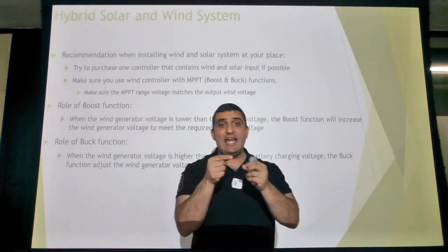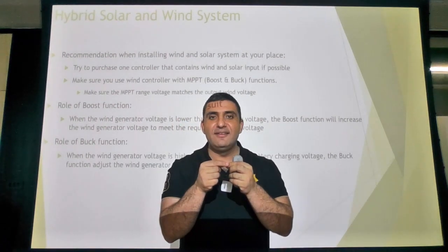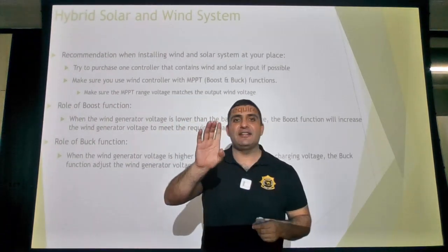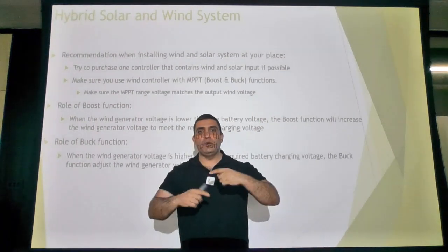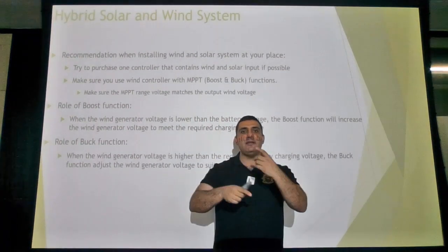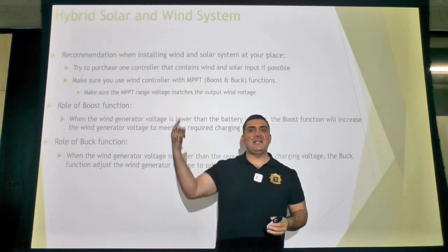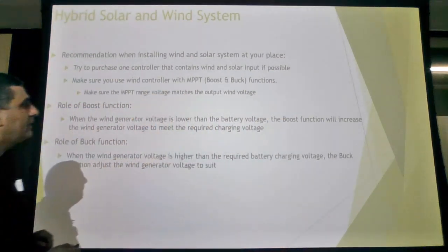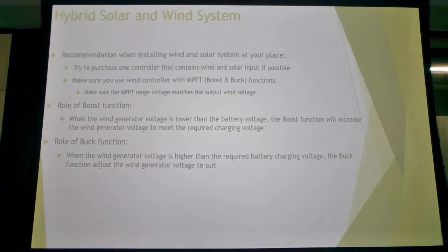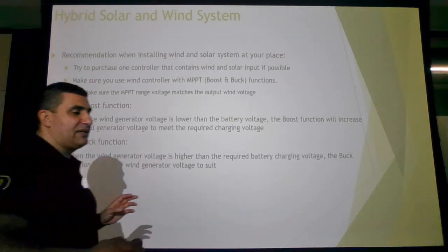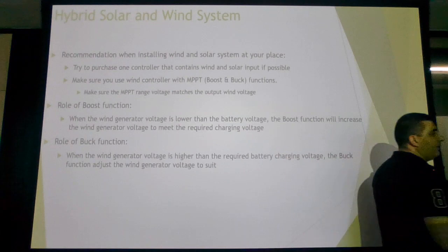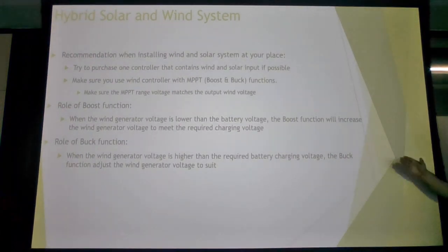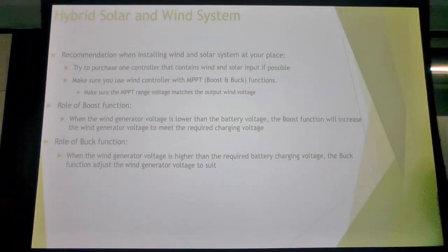If you don't have this function, under small wind you will not charge. The wind turbine will be running, but there will be no output power contributed to your system. So that's very important, guys. Remember this. Whenever you go and buy the system, you should look for these two functions.